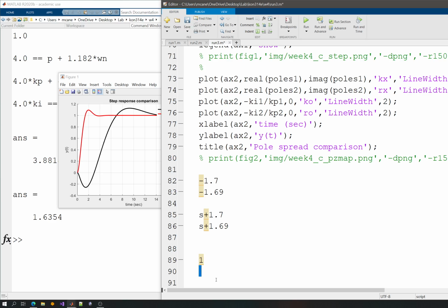There's no measurement. So if you're comparing closed loop and open loop, the closed loop system is economically a little bit expensive, since sensors are expensive, but you're restricted on that, because if you want to have a high precision control on the room temperature, of course you have to go ahead and measure the room temperature.